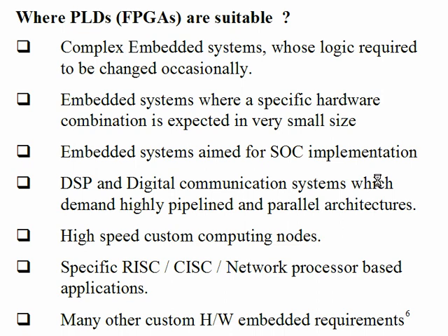See, for example, if I use a DSP compiler in this, will it be called a cross compiler? I am using an Intel machine, which has an Intel P4 processor, and I am using a compiler which can generate the object file and the corresponding hex file and everything for a DSP processor. Can it be called a cross compiler? Yes, it is a cross compiler.